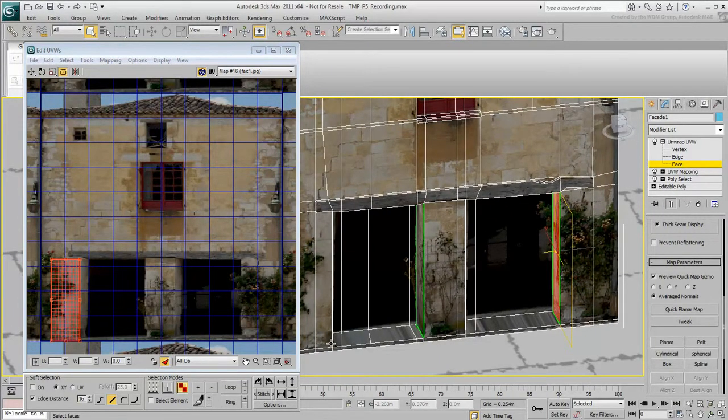The door steps are a little tricky because the photograph has no information about that portion of the building. To compensate, you can use the lintel texture. Although the lintel is wood, when scaled up in size it can pass for stone.